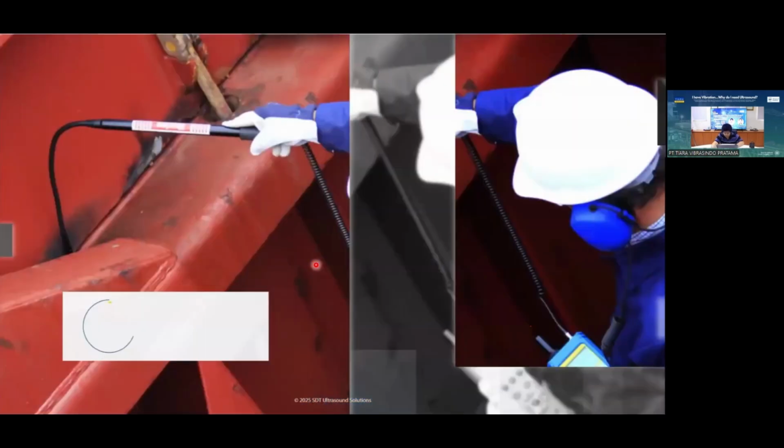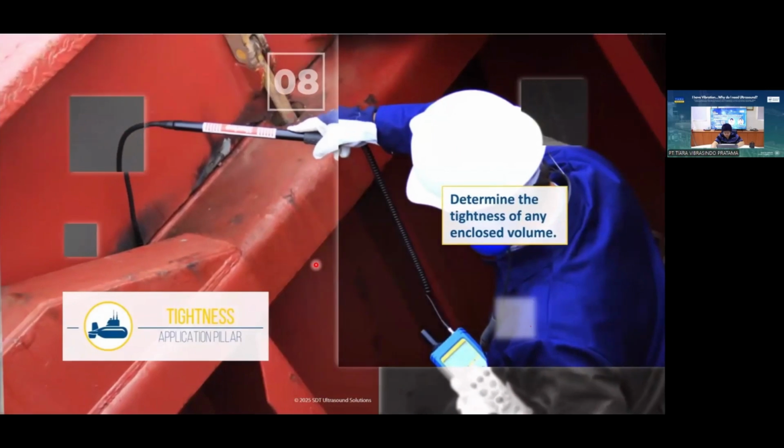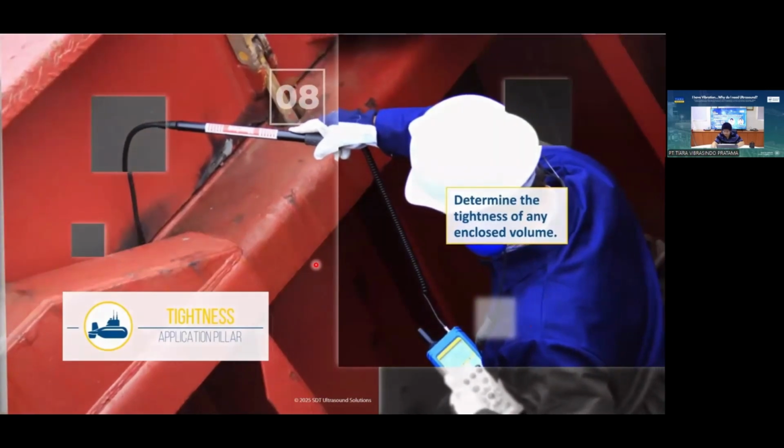The last application is the tightness application. It's very famous in the marine business, car manufacturing, or the airplane business also. Because every time you maintain a ship, you have welding inside. If you want to know whether your welding is cracked or in good condition, you can put an ultrasound generator inside on the opposite side, and measure with the airborne sensor to scan if you can detect the sound from your welding. That means your welding is in bad condition, because maybe there is an internal crack.